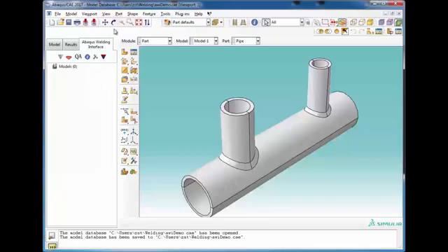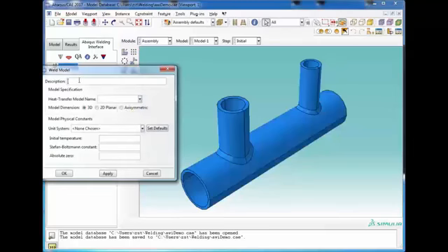Once all that's done, we get to the point where we're ready to work on the Abaqus Welding Interface. The first thing we do here is right-click and say Create, which doesn't necessarily create a model, but just initializes some things that we're going to need in the model. When we're working in the AWI, we typically are going to be working on the heat transfer model. And at the very end of the process, the AWI will automatically generate a stress model. So the sequence is, it uses a sequentially coupled analysis, does the heat transfer first, followed by the stress model.